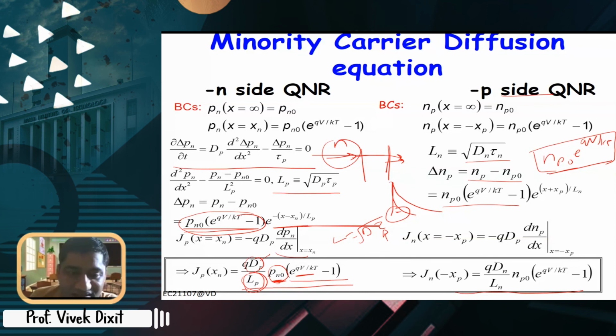But if you decrease the doping on one side, other factors will come into the picture. But if you consider a one-sided junction, in that case you can see this effect very carefully. For a one-sided junction, if you increase the minority carrier concentration of the other side, the current will increase. So that means you have to decrease the doping of the other side in case of a one-sided PN junction. We will see that now.